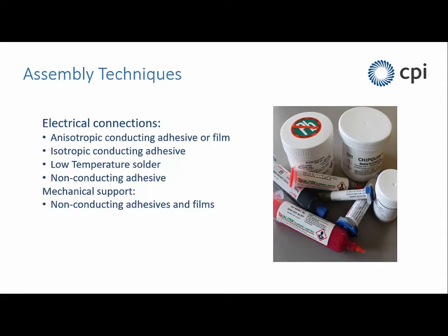And so a number of materials have been identified for this type of approach that use conducting adhesives. And there are two key forms of conducting adhesive, anisotropic and isotropic, and I'll come back to those shortly. There is an area of low temperature solders, and there are solders that will operate down at about 140, 150, probably 160 degrees, so they will operate perfectly well at that.